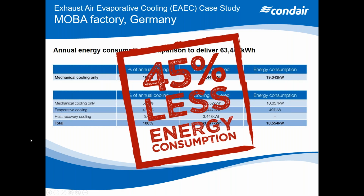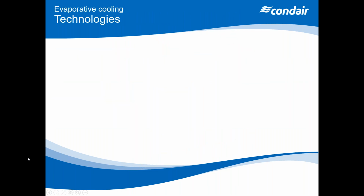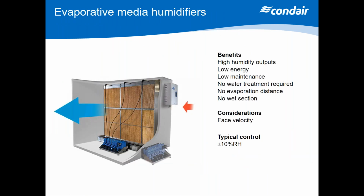So there are various means of doing evaporative cooling, and each application lends itself to a different specific strategy. So that leads us on to the technologies that are required to deliver this sort of cooling. And the first technology that we're going to look at is an evaporative media humidifier, and it is the most common, most popular type of evaporative cooling system.